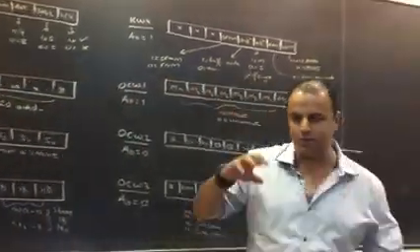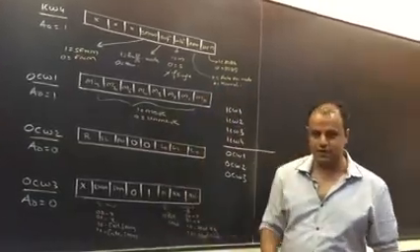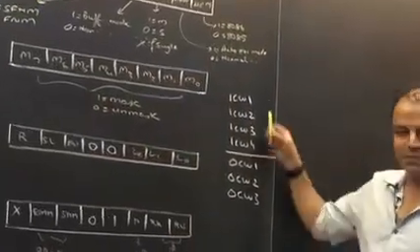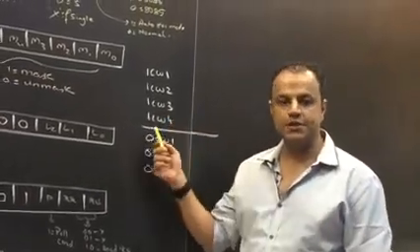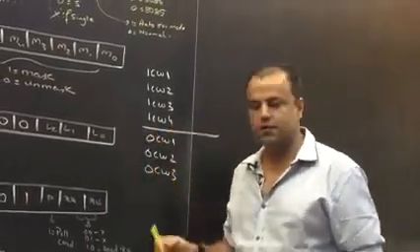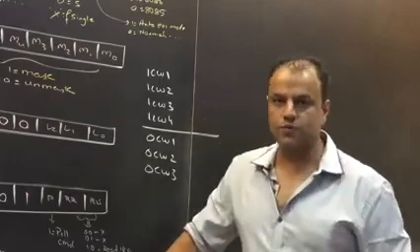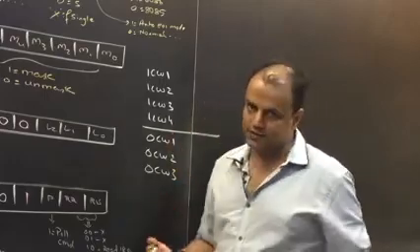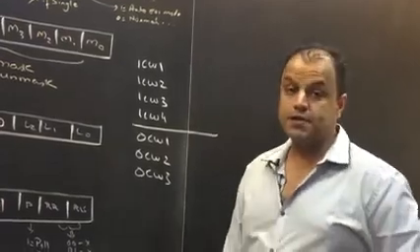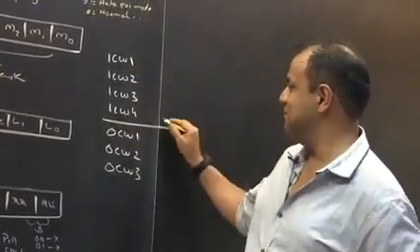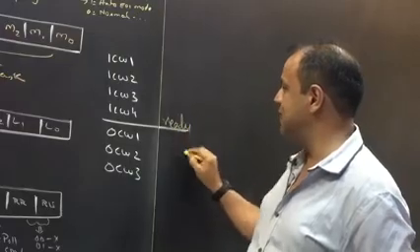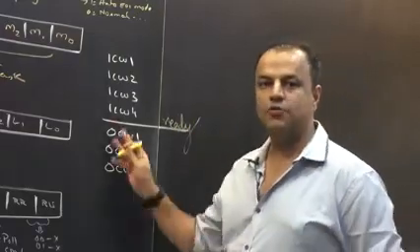Now, let's give you a brief idea what these commands are before we start learning them. These commands are divided into two categories. They are called ICWs and OCWs. Initialization command words and operational command words. As the name suggests, what will we give first? ICWs. That's how you initialize 8259. You know, initialization of 8259 is compulsory. That means doing this is compulsory. This is where 8259 will become ready once you have given all the commands.